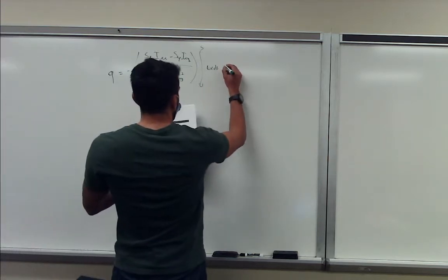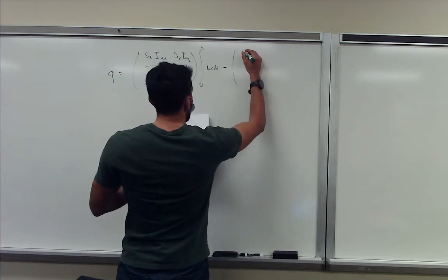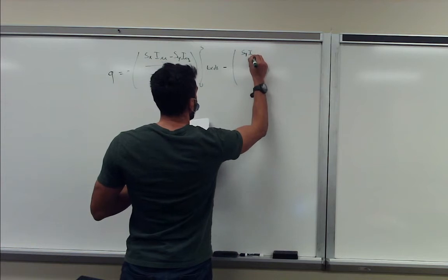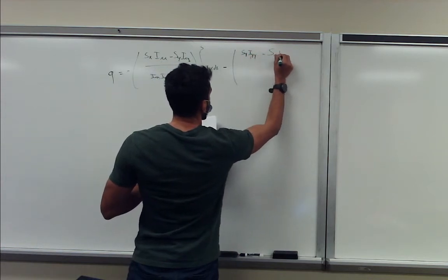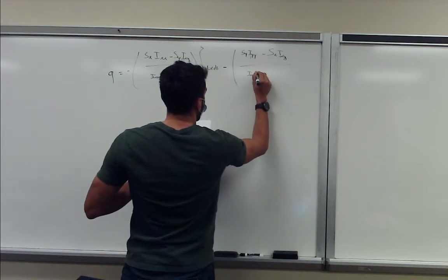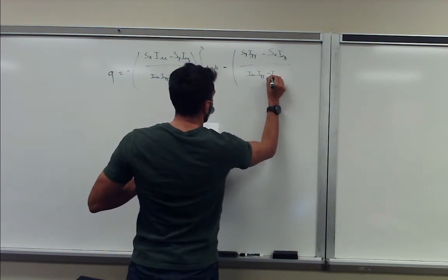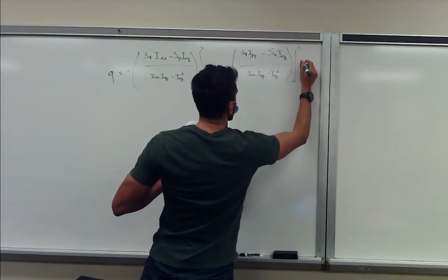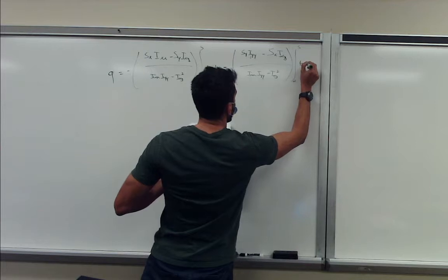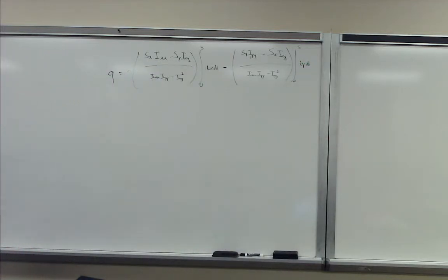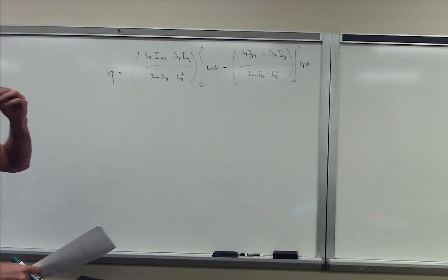And then we have a second part to it, negative: Sy Ixy over Ixx Iyy, minus Sx Ixy, and then the integral from 0 to s of ty ds. So that will be our most generic form of our shear force and shear flow equation.